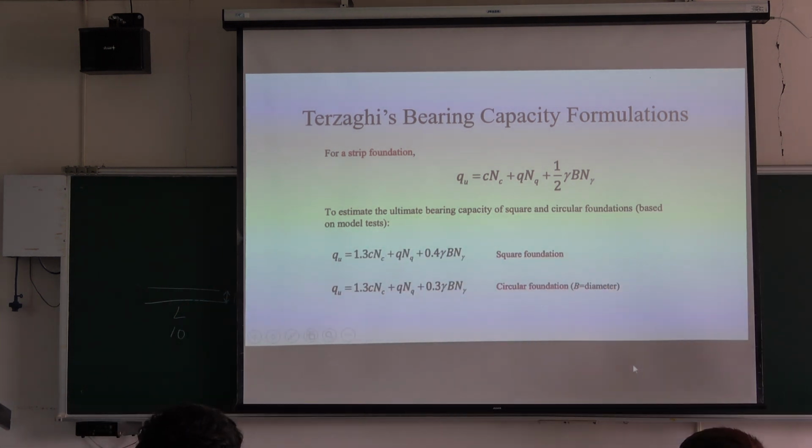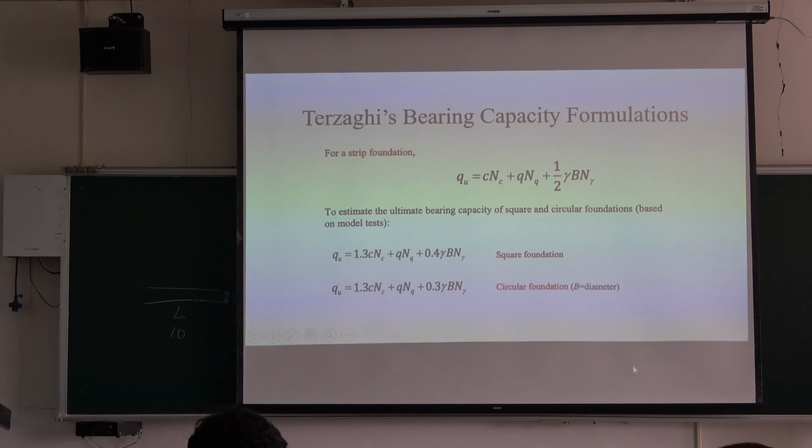Okay, so what I was trying to say earlier is, for example, this is our foundation, right? We get this. So we say here to here is the depth of the foundation, right? So if we keep increasing, this goes down, okay? That means df goes up. Then we say this Qu will go up, right? That means the soil here is uniform, the same type of soil. Okay, it's the same, but let's assume now, our foundation goes all the way down here. We make it deeper.